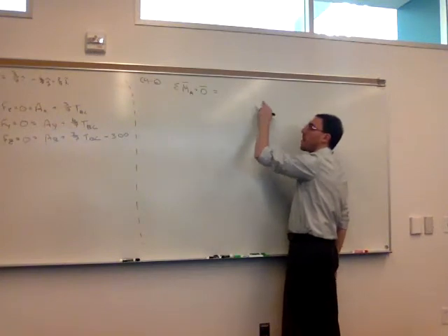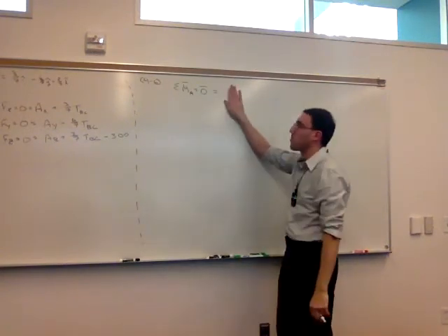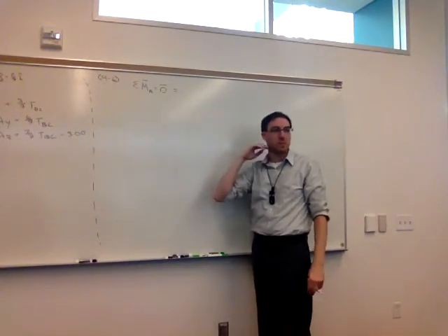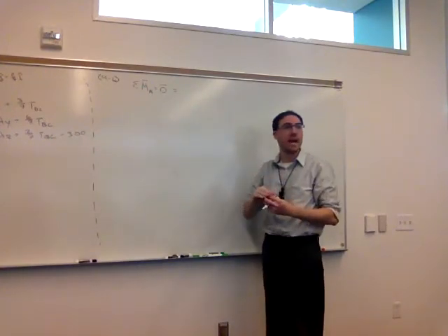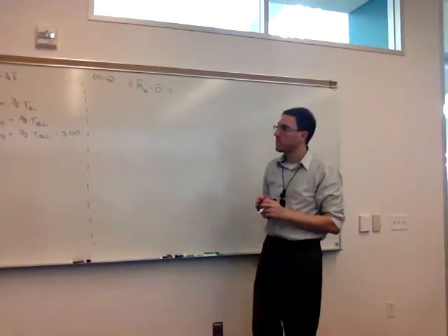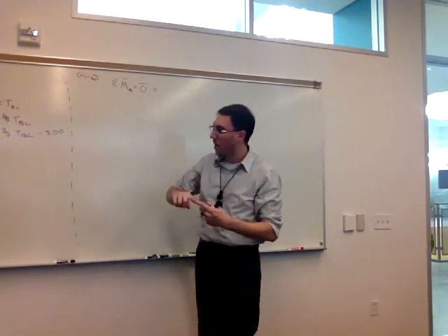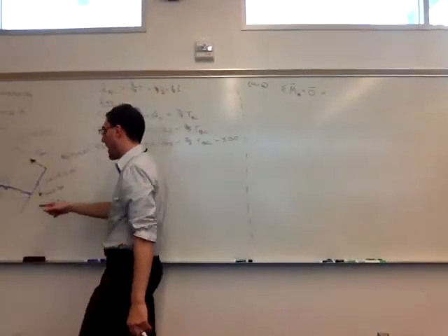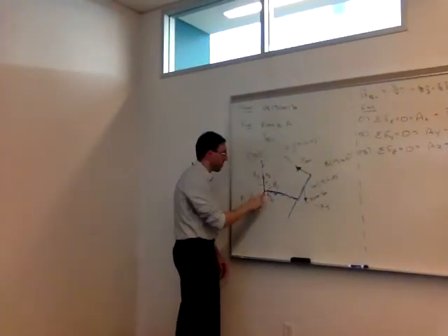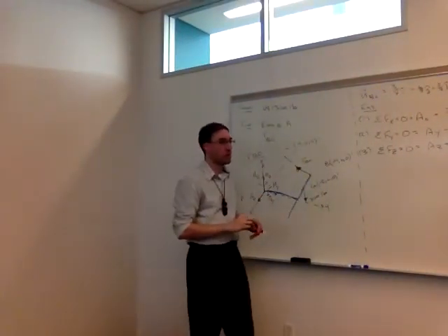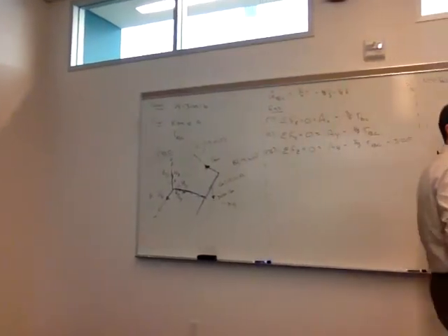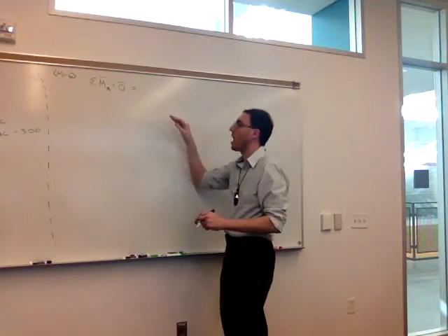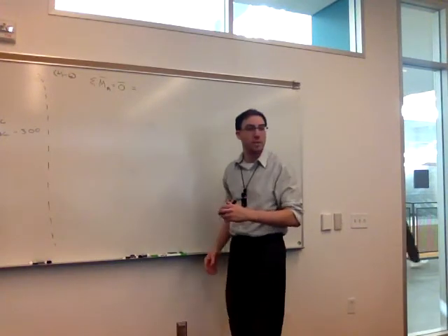All right, so in variables, what's the right-hand side of this going to look like? So what contributes to the moment around point A? Ay, Az, and Ax all act directly on A. So the position vector would be RAA, which would be 0. Right. So the couples or the moments do. This is where we have to be careful, and this is a common kind of omission that people make.